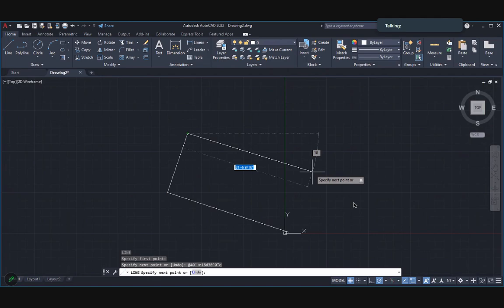So we're going to put in our first distance, which is 80 feet, and then the angle sign, and then I can do one backspace and then type in S for south, and then 71, letter D for degrees, and then 30 minutes, and then 0 seconds quotation, and then type in E for east, and then press enter. There you go.